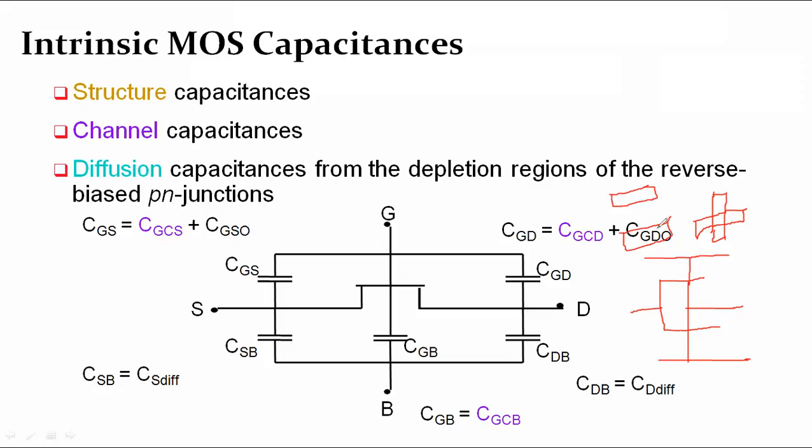Here this produces a parallel structure. When they form a parallel plate, automatically capacitance comes into the picture. Two conducting layers: when two conducting layers come, capacitance comes into the picture. Here the crossing area is small as compared to the parallel plates. When we use layers that are orthogonal, perpendicular, here also a metal layer is perpendicular to the diffusion layer. In this case also the capacitance is less. When we use a perpendicular layer, the capacitance value is less. When the capacitance value is less, delay is less.